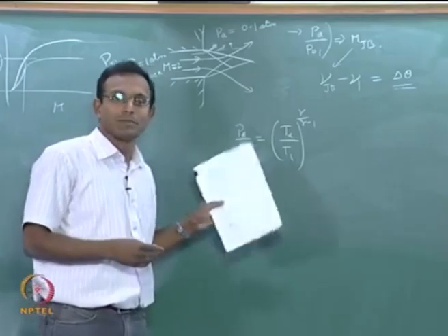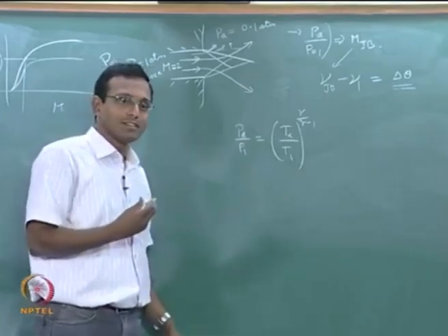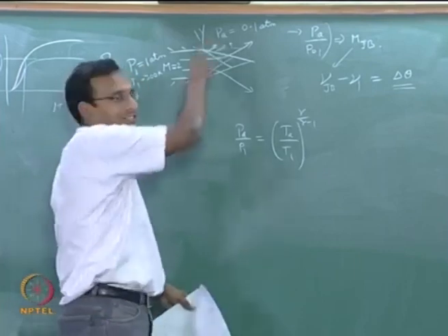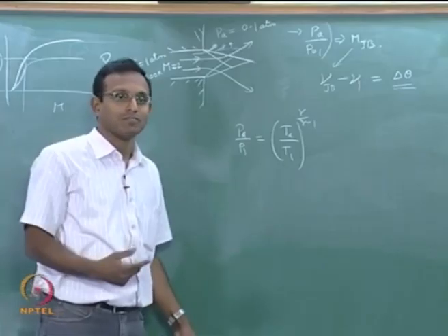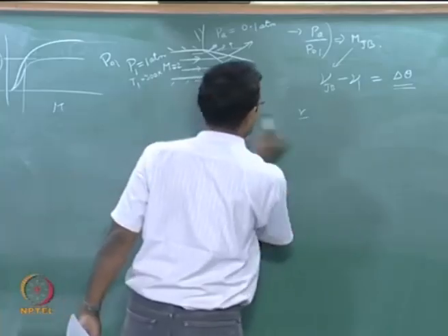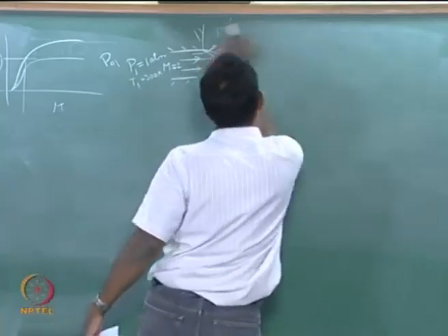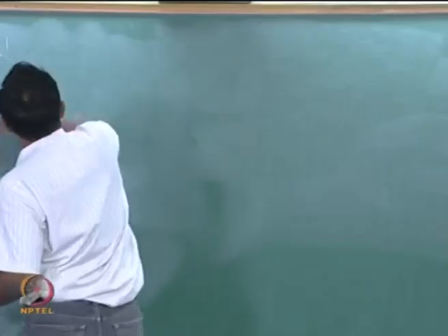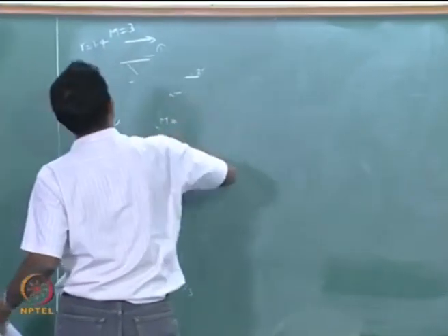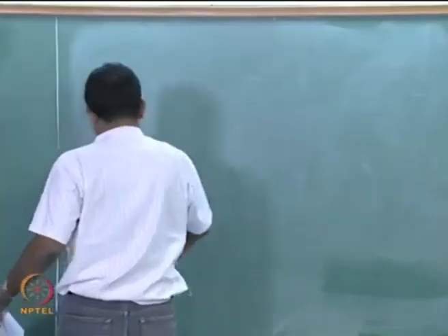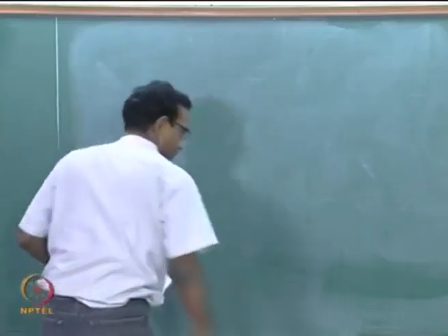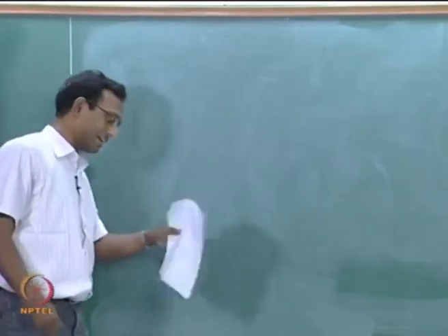Why did I pick this problem separately? All this time we have been considering boundary conditions as velocity vector direction. This is one problem where pressure at the exit is given. Pressure is the boundary condition given for the flow direction. Two boundary conditions are typically used in the gas dynamics world. Once this is done, the next step is just to use this expansion fan concept along with all the previous compression wave concepts you have, all that mixed together in flow situation applications. That is the only thing left.